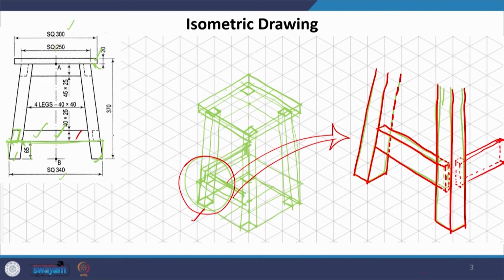Exactly the same thing will happen in the top, but a large part of it is going to be hidden underneath this square part, because this is the top part. So, when you draw, you must try to draw all the dotted lines in place. Okay. So, if I do not draw any dotted line, this is probably what we will be seeing, only the solid part, and this will actually be tucked in beneath the top square.